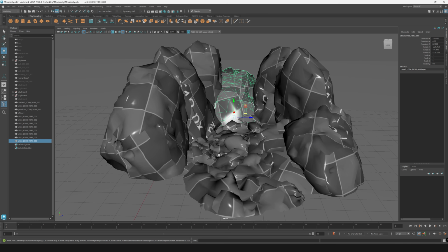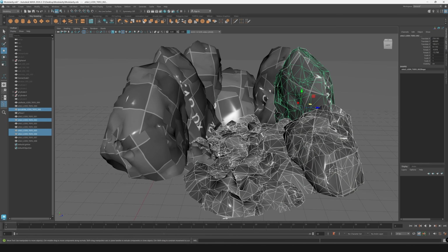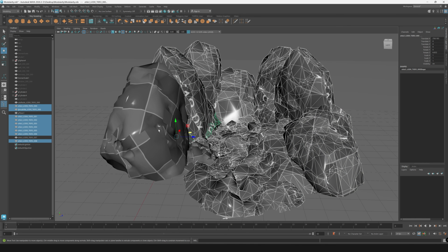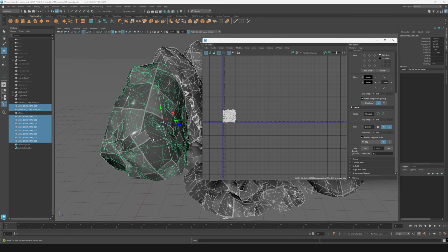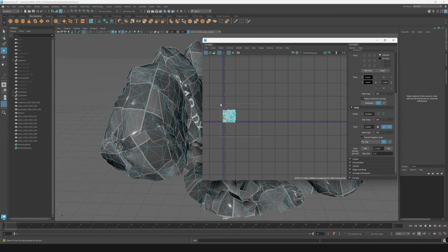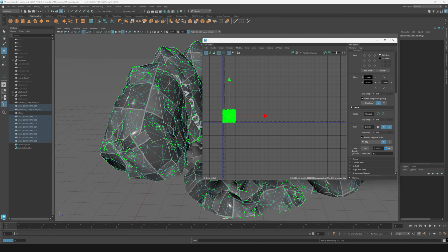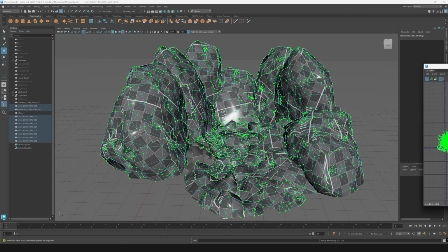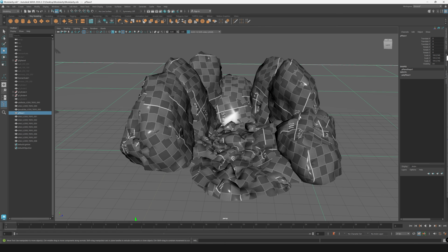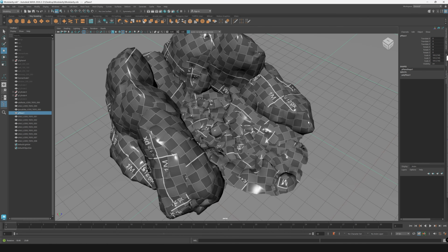to make things feel so much more cohesive. So typically you would probably want to either make your own through things like ZBrush or photogrammetry and try to make sure that they have a similar shape language to them. Once you make one of them, make sure you set the UVs in a way so that they have the proper texel density. Like here, if I select all of these guys real quickly, this is what they'll look like when we actually have the proper texel density applied to them. There we go. Perfect. See, a lot more consistent looking, kind of matches a lot better.